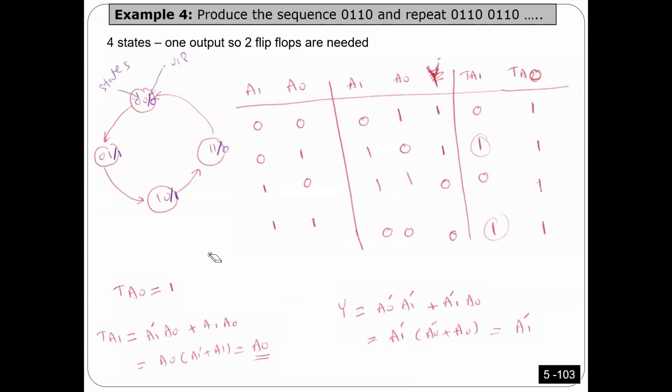Look here, guys. Now, number 1, how many states do you need? This is the first question. In this case, every bit here in the sequence is 1 state. That means I need 4 states. Here, the number of states equals the number of bits in the sequence. That means if I want to get a sequence that's 8 bits, I need 8 states; 3 bits, 3 states, and so on.